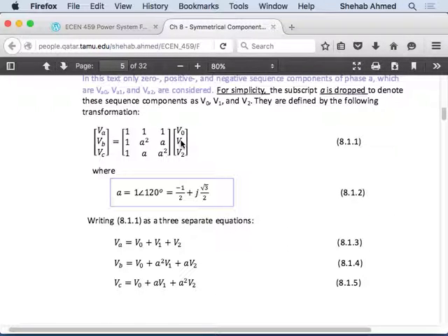If I don't have zero sequence, there's nothing flowing in my neutral. If there's nothing flowing in my neutral, what type of fault is it? It's going to be a line-to-line fault. That's the only option. If the zero sequence component is 0, that means I don't have anything connected to ground. There's nothing connected to ground. There's nothing flowing in my neutral.